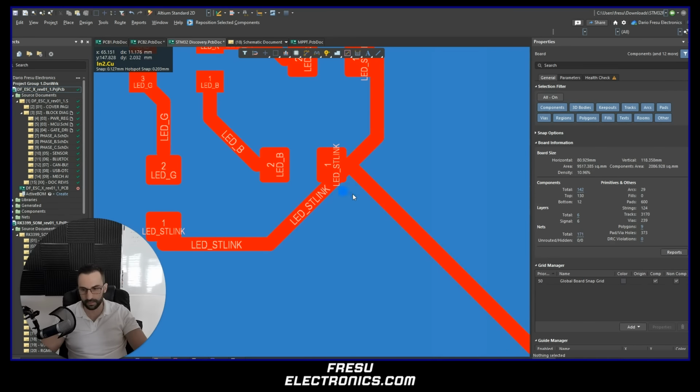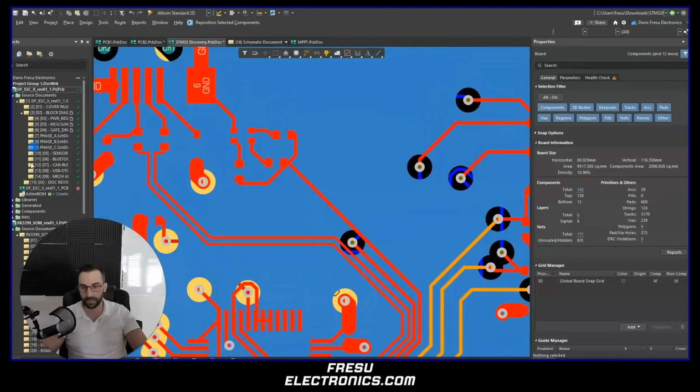So don't create impedance discontinuities. Use a controlled impedance trace. Typically for signal traces, we use 50 ohm, because most drivers have a source impedance of 50 ohm or an input impedance of 50 ohm.